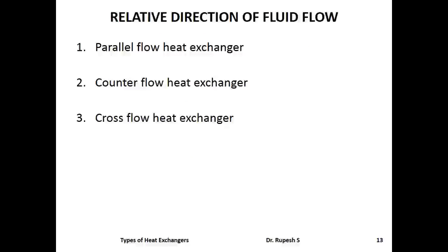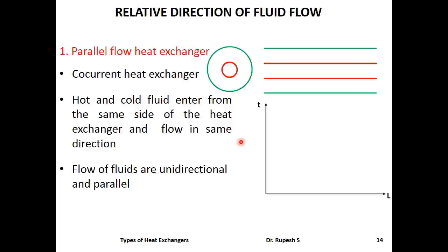Based on the relative direction of fluid flow, heat exchangers can be classified into parallel flow, counterflow, and cross-flow heat exchangers. In a parallel flow heat exchanger, both hot and cold fluids flow in the same direction within the heat exchanger. Here, hot fluid flows through a pipe in one direction, and cold fluid, which surrounds the pipe, flows in the same direction as the hot fluid.